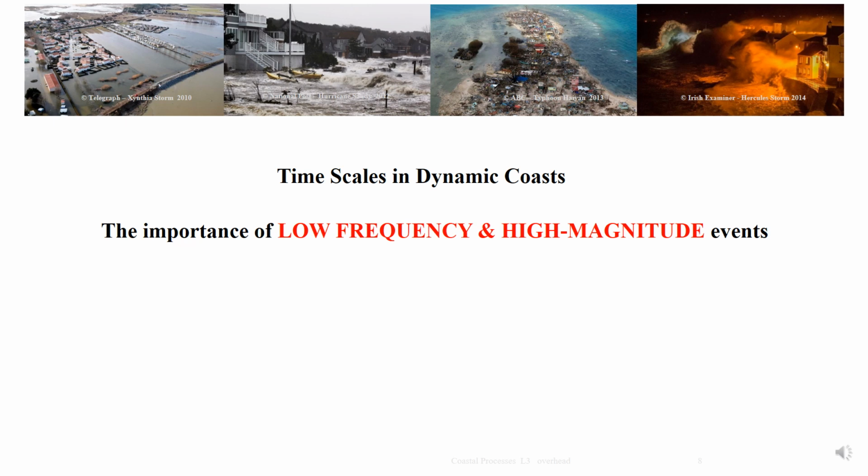It's important to look at timescales within dynamic coasts, and particularly the importance of low frequency and high magnitude events. These things are not happening very often, but when they do happen, they contain a huge amount of energy. And this gives us coasts or coastlines that respond very, very rapidly to these events.